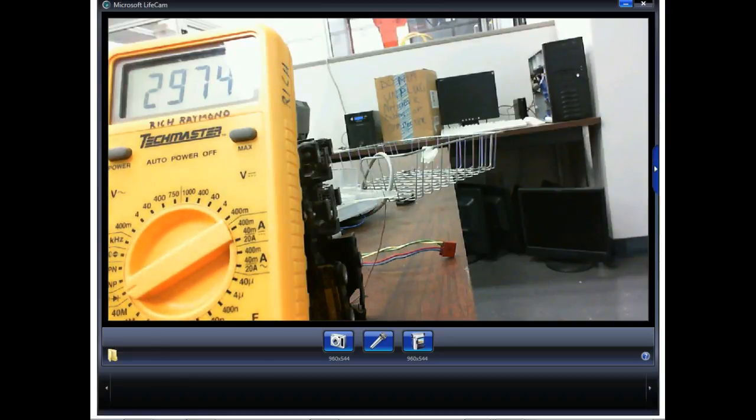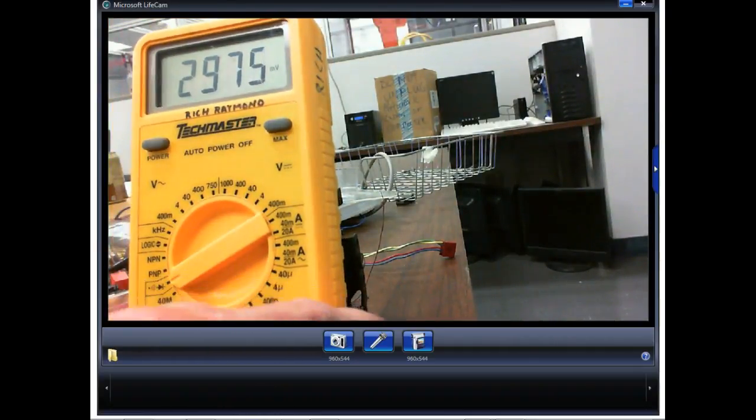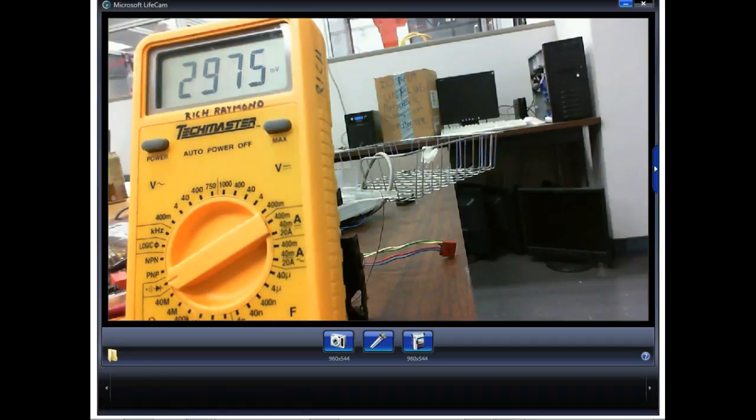So y'all, if you got your meter, you got that diode scale on there, and you can check these things. And when you get into solid state, we'll show you how you can use this to check transistors. You can use it to check FETs or bipolar transistors. It's a neat little scale on your meter. You check it on the scale that's got the little diode on it. See the little diode symbol on there?